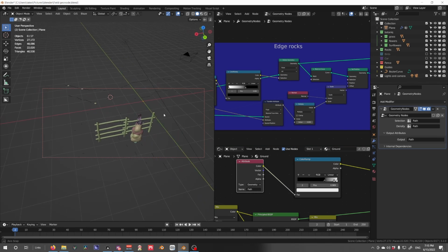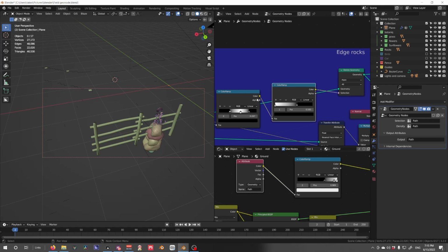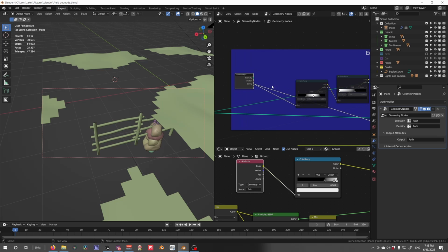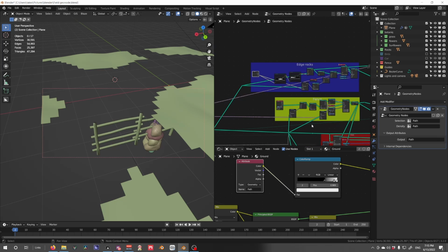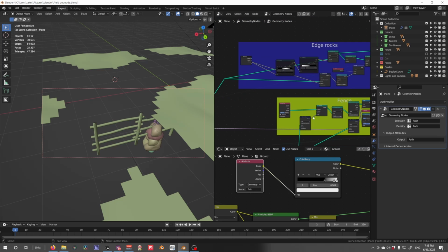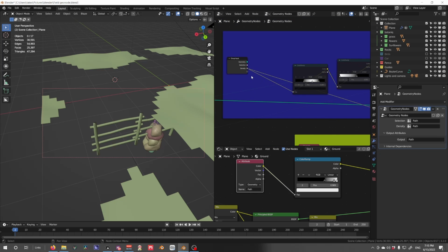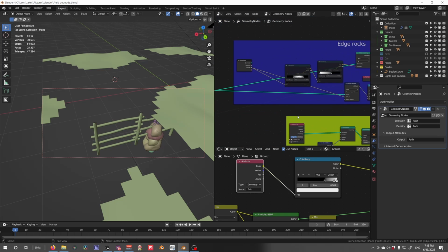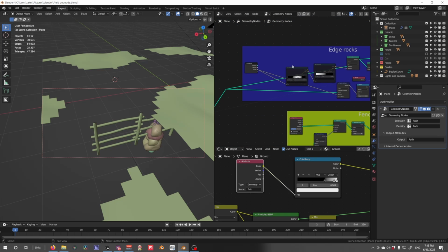So you see that I deleted it in a way where if I mute these, based off of the density of the geometry node, and all I did to get the density was add this into the socket and then disconnect it, because I didn't need it connected, and then told the density to become path. After that, I had access to the path on the density channel without actually having it affect the actual density of my grass. You could also do it another way, but that's the way I've always done it, so I just do it that way.